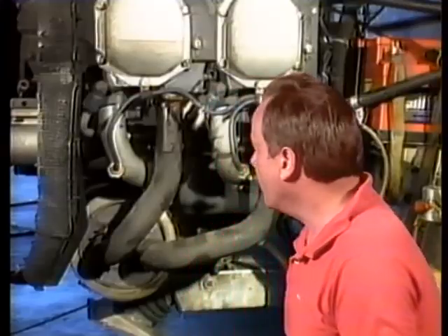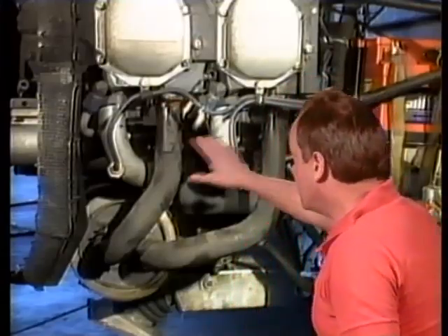So they're saying take off this shroud every now and then and look at the exhaust system itself. All right, reciprocating exhaust system leaks are a bad thing. And so how do you tell when you have an exhaust system leak? Well, you might see soot. That's a question on a test. You can detect exhaust leaks by signs of exhaust soot inside the cowling and on adjacent components. So if you see soot around here, it tells you you might have an exhaust system leak.